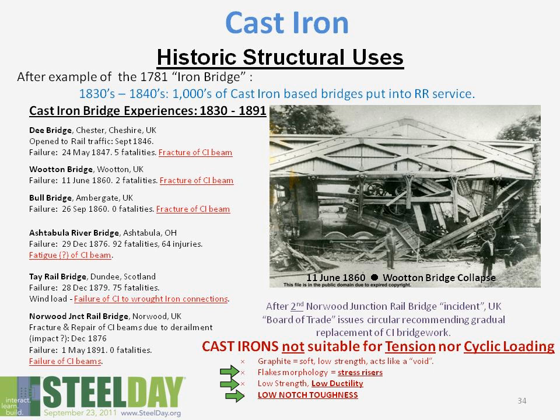Between the 1830s to the 1890s, there were a fair number of cast iron bridges, mostly put into railroad service. There were a lot of incidents. The photograph here clearly shows a locomotive under the bridge, obviously not a good situation, and we see places where the cast iron beams have clearly fractured. Again, due to the nature of cast iron, they're not suitable for this type of application.